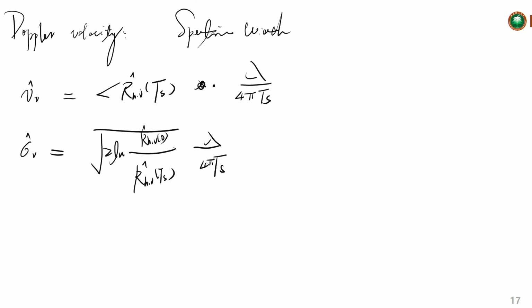And so we also need some more algorithms to obtain how this is affected by other factors, like the noise. As we mentioned previously, we set the noise to be 0 for the simplification of our analysis and demonstrations. But actually, for the radar system, the noise can cause some bias and also some extra errors in the moment or variable estimates. And so what we need to do is correct this bias caused by the noise.